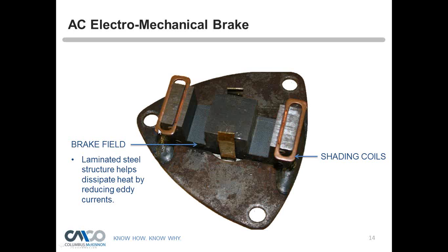And it's not a direct comparison, but similar to how a capacitor would work for a start motor, that it would lag behind line voltage and create the magnet to help the motor keep spinning. Well, the shading coils, in a sense, do that for magnetism. And if those were to fall off or get damaged in any way, then you hear a lot of chatter or a loud humming noise, and the brake doesn't operate quite right.